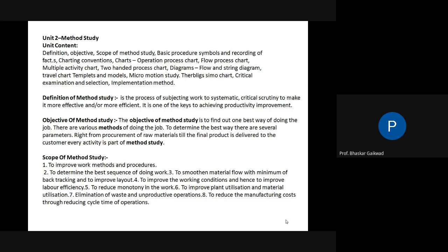This is one example. And second example, for example, nut and bolt manufacture. Continuously, we are manufacturing nuts and bolts. So starting from the raw material to the finished product, whatever machinery we require should be in one line. This product layout is also called line layout. So all machinery should be in one line so that once the raw material enters the first stage, it will go on processing and ultimately the final product will be there. This is the smooth movement of the raw material up to the finished product.